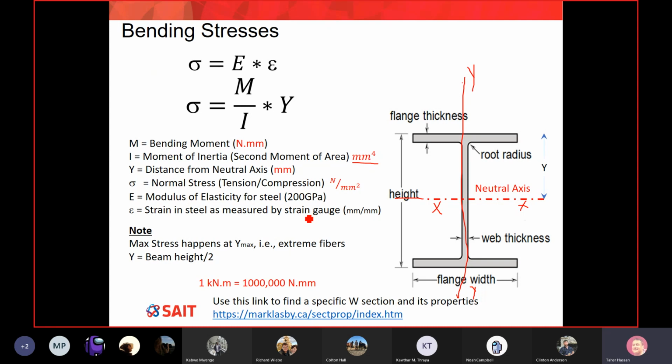Really, please mind the units. Normally, how do we measure sigma? What are the units for stress? By now, you should remember that. Anybody remember from the tension test or compression test? Newton per millimeter squared. Thank you, sir, which is MPa. So if we get this in Newton per millimeter squared, what should we be doing on this side? If I want the left side in Newton per millimeter squared, everything on the right side must be in millimeters. So let's test.